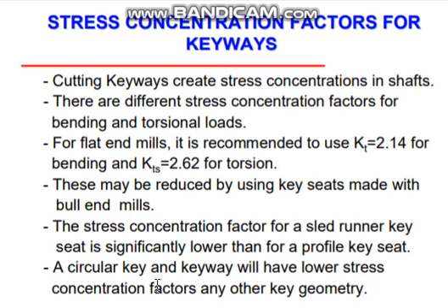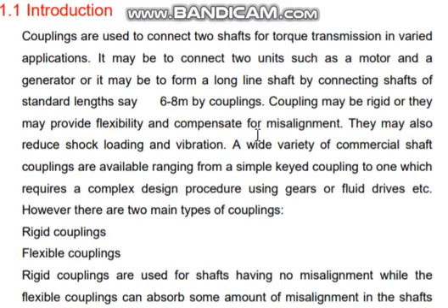A circular key and keyway will have lower stress concentration factors than any other key geometry. But anyway, you have to make a tight fit of the assembly, it seems. Okay, I think that's all we will discuss about the keys. You go through the textbook and if any other points we have missed, you can go through.